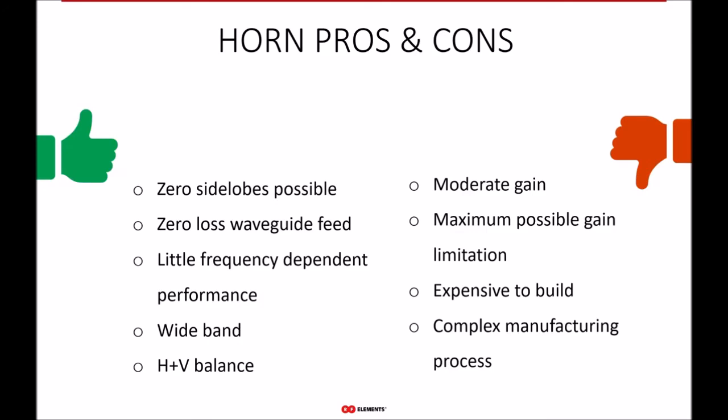The bandwidth of operation of horns is quite wide. I mean, definitely wider than the patch array antennas, and actually the higher you go in the frequency, the wider that single mode bandwidth becomes. So it actually only gets better the higher you go in the frequency. And not to say, of course, also the balance between the chains is important for that really high quality performance and customer experience. But of course, the gain of the horns is moderate.